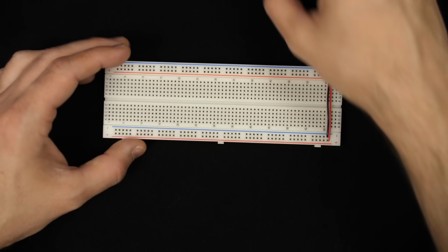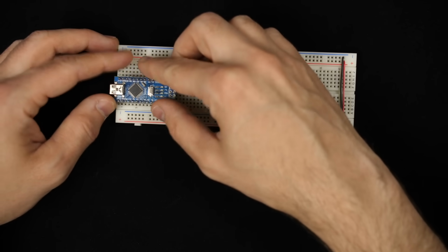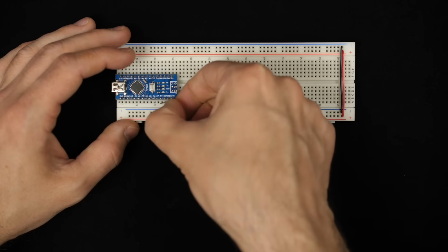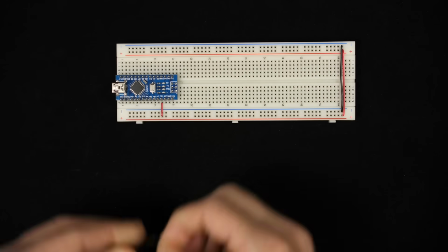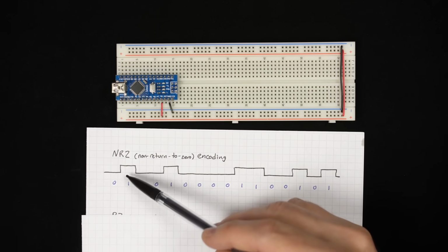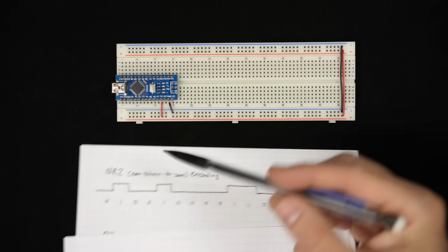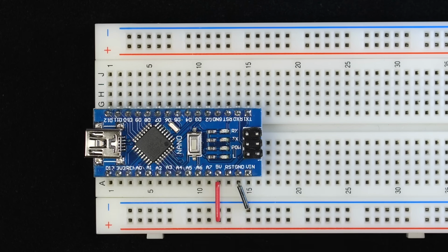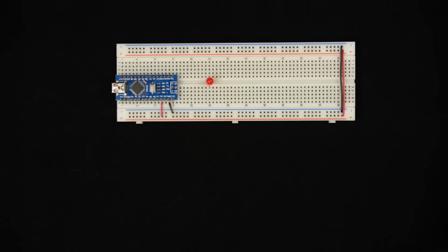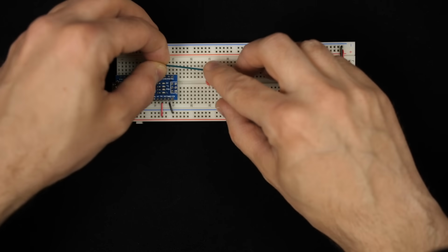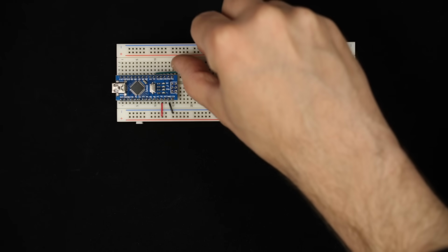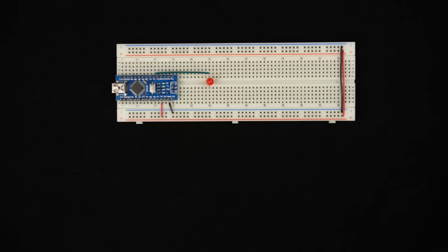So let's hook the first Arduino up and get it to transmit some data. So I'll connect it to a breadboard here, and I'll hook the 5-volt pin and the ground pin up to the power rails of the breadboard. And then for NRZ data, we just need a single data signal that we can control to go high or low like this. And so we can use any of the digital pins on the Arduino here. So I'll hook up an LED so we can just monitor whichever data pin we're using. And I'll hook this LED up to one of these data pins. And let's see, I think it's D3 maybe. So our LED's hooked up to data pin D3 on the Arduino.